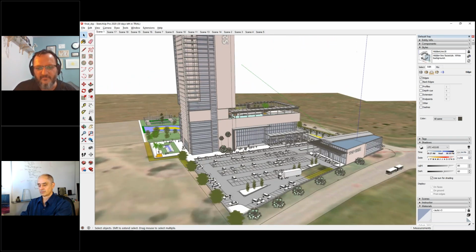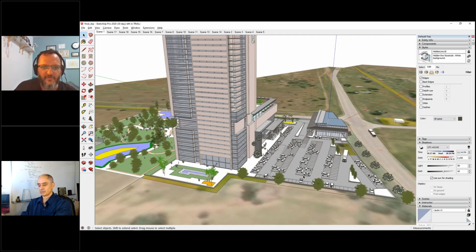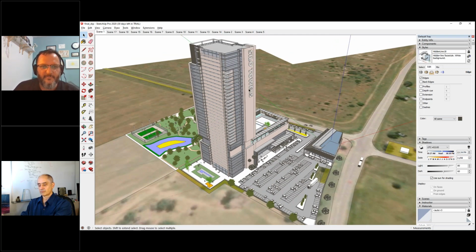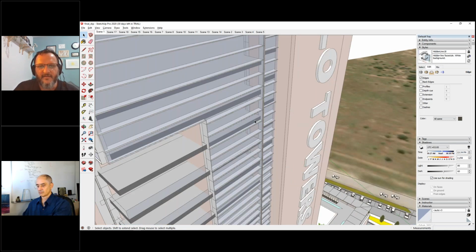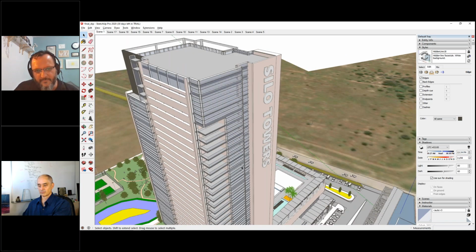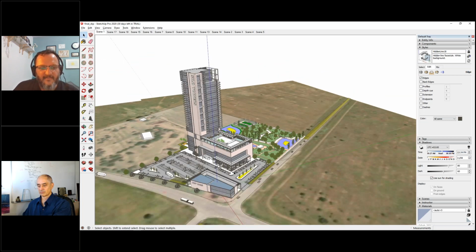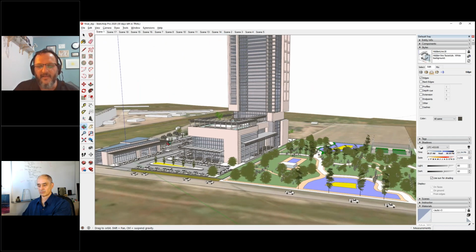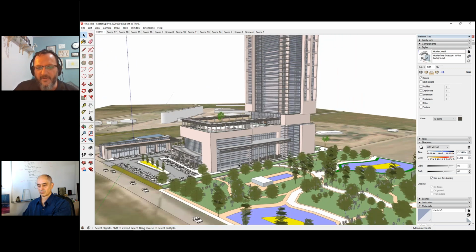And if you take a look at this model, there are different elements at play, and normally for a building, if you actually break a building down into its basic components, what it's made up of is a series of floor slabs. You can see these floor slabs over here. It's made up of curtain walling systems. It's made up of solid wall systems, and then basically detail components. And that is really what buildings are made up of. And you need to vary those components as you are working in your CAD environment. So there are 3 to 4 components that you just need to play around with.